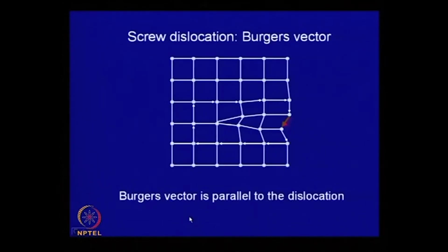And here, look at that atomic arrangement. I have tried to draw that, and here also, to determine the Burgers vector, you have to construct a Burgers circuit, which is shown over here. So, this part, that arrangement is perfect, possibly here this is perfect, around this there is a distortion, and this is the slip step which has formed.